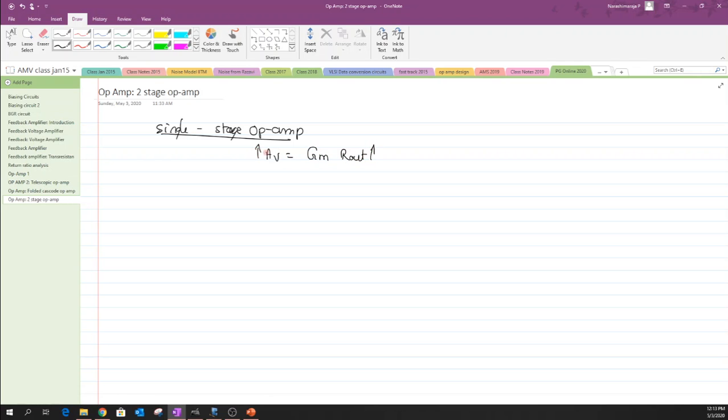So we were working on this R out quantity to increase the gain, and to accomplish this, we tried to stack a series of transistors, but doing so we ended up with a low output swing. This is something that we were losing when we tried to increase the output impedance.